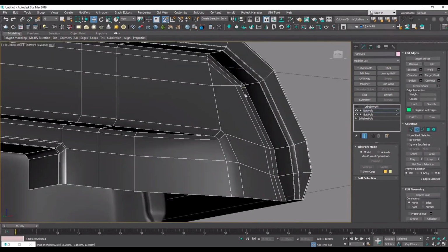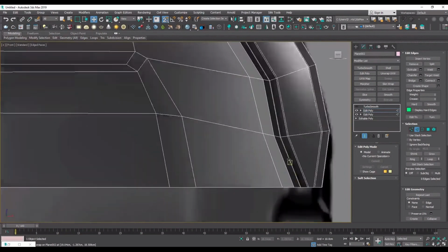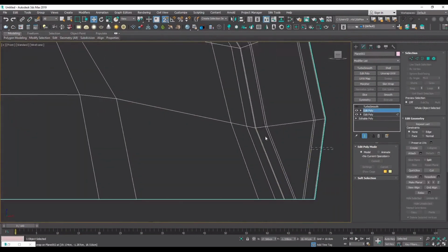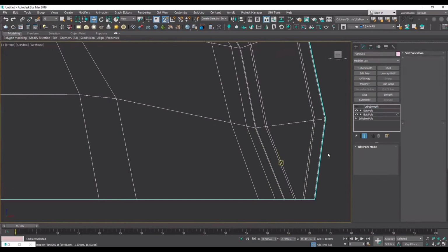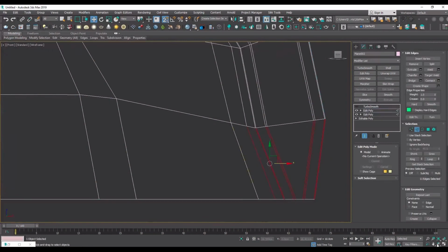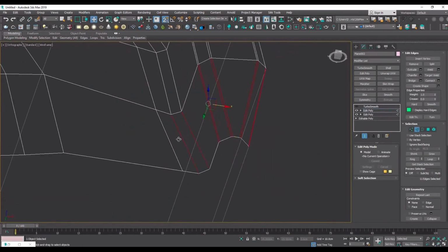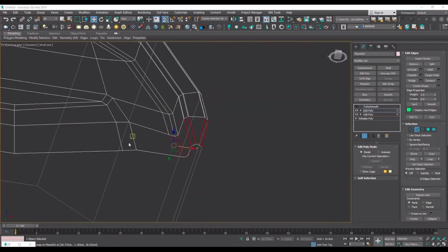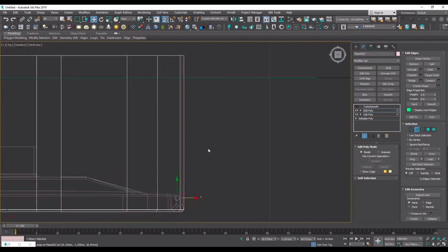So, and you might just ask then, why did I add this edge despite I already added some supportive edge loops? Because it's not supportive, it's being a safe margin for this part. I'm going to actually connect these edges that I have here, and I added that edge loop because I'm going to have a floating vertice and I don't want it to corrupt the shading on the left where it bends down and goes down.